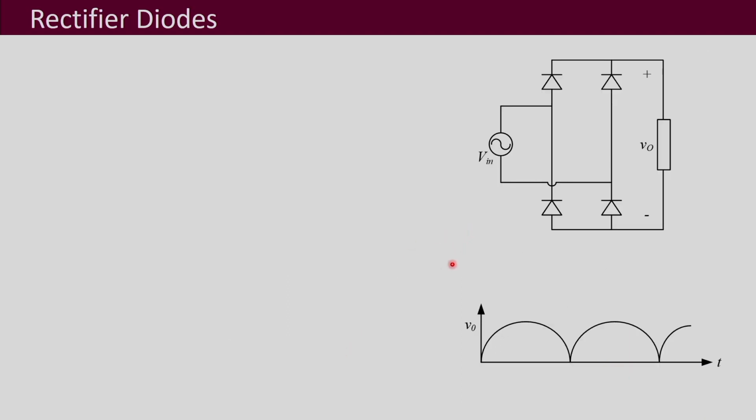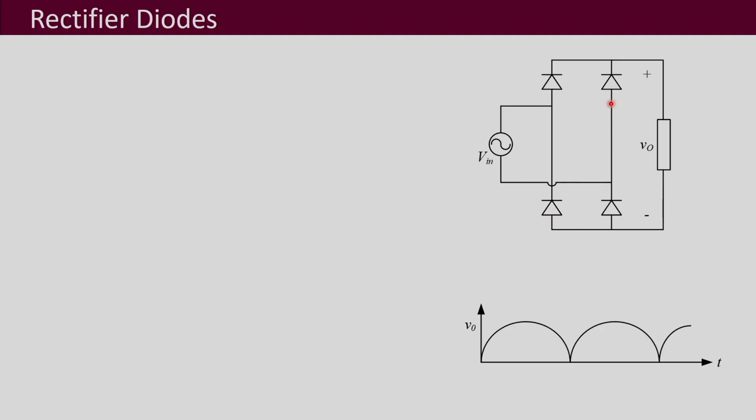Now, let us see what the different types of diodes are that are required for different applications of power electronic circuits. Over here I have drawn a rectifier, and usually the supply voltage will be your known 50 hertz supply voltage, and the current ratings of these diodes may be very high when rectification is happening.